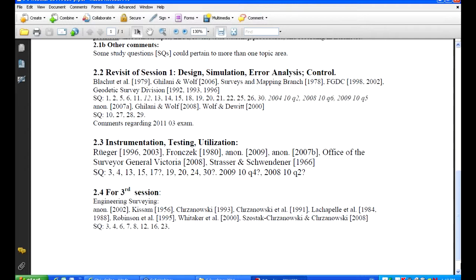In the earlier days of EDM measurement, most systems would be with a standard deviation in the order of centimeters. If you were really lucky, by the mid-80s, it would be down to about 5 or 6 millimeters. The electronic fidelity of the instruments wasn't very good, simply because the diode that generates the frequency would sometimes age and start creating problems.